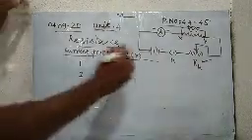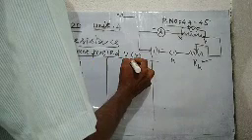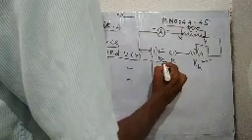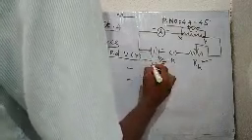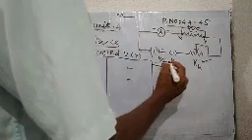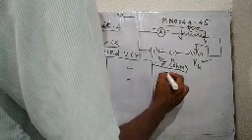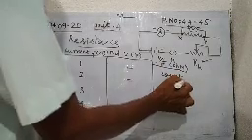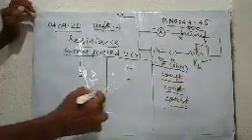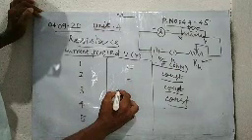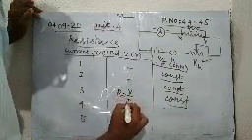Okay, then in each and every case, if we divide the V by I, that is the potential difference across the conductor divided by the current flowing through the conductor, then we get V by I, which is found to be almost a constant for each and every value of current and voltage. Then this constant is the resistance of the nichrome, that is R is equal to V by I ohm.